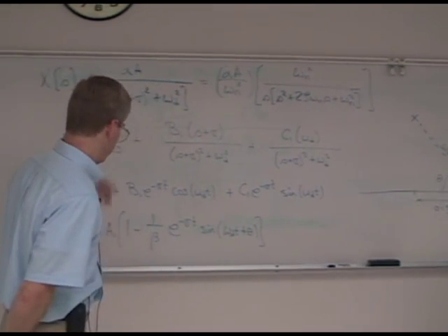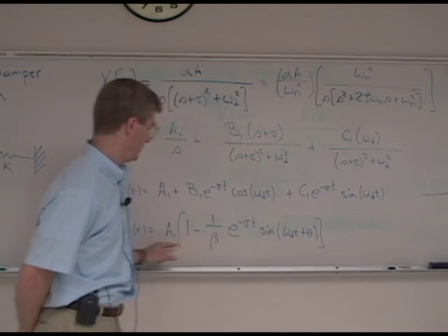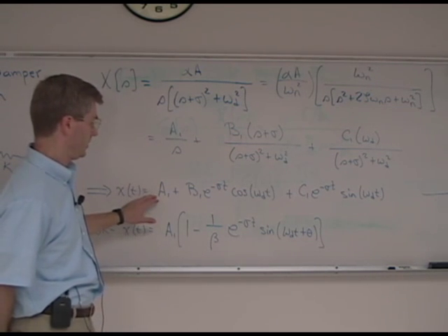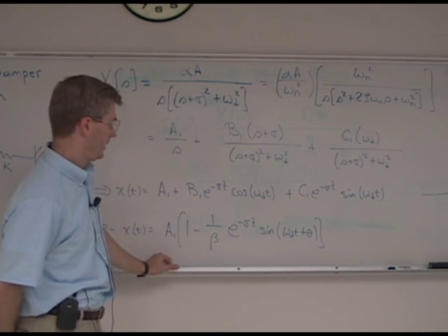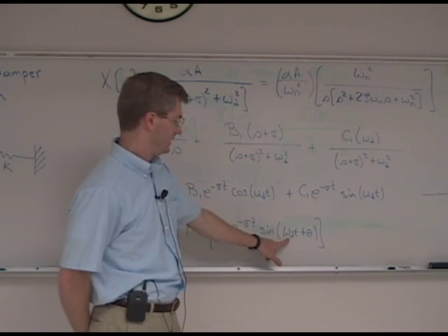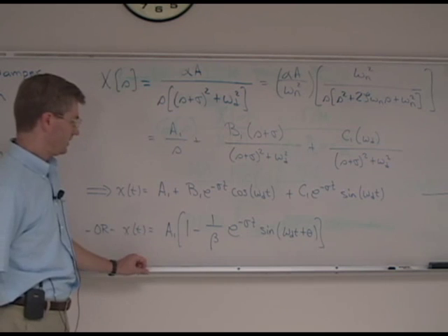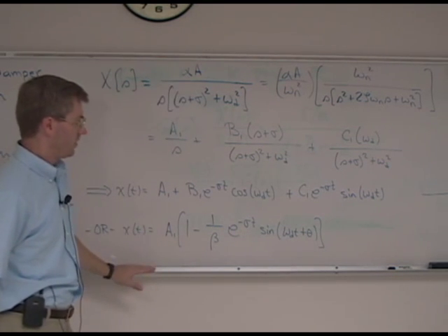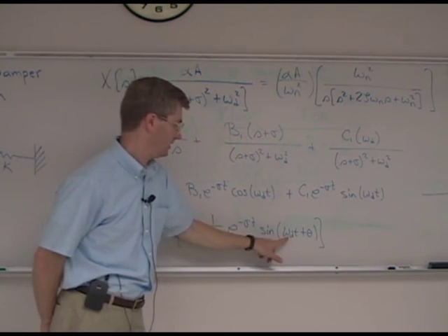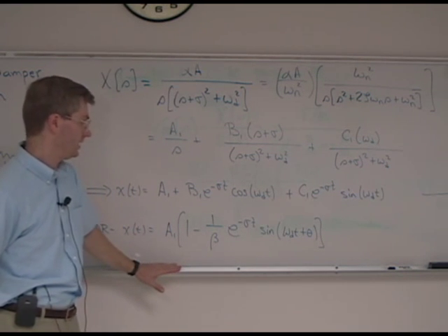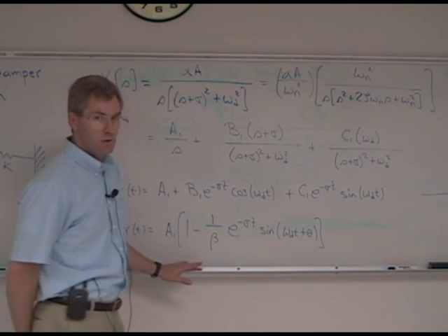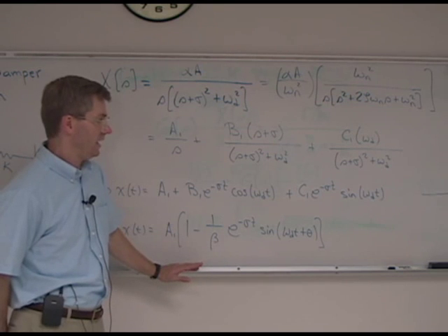What we want to do now then is use this information to determine from the transient response, or from the step response, what these different values are, and in particular, what is our damping, sigma, what is our damped frequency, omega sub d, and what is our alpha term in our original transfer function, G of s. We're looking for alpha, sigma, and omega sub d, and then we can define our transfer function, G of s,